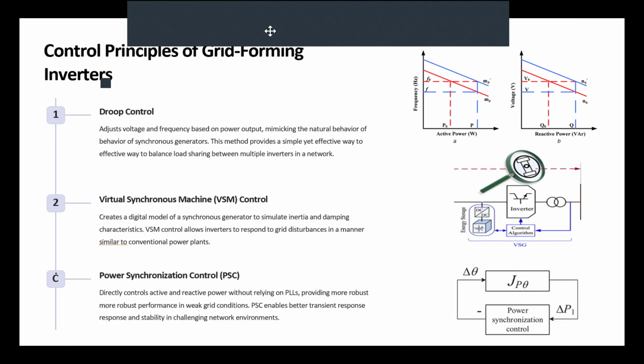We are going to talk about how it's happening later on in detail, but I wanted to just give you an idea. The load increases, but what the inverter sees is that the frequency of the grid is decreasing. It's overloaded, so I have to push for frequency. Does that make sense? So it would mandate more force to stabilize the frequency.